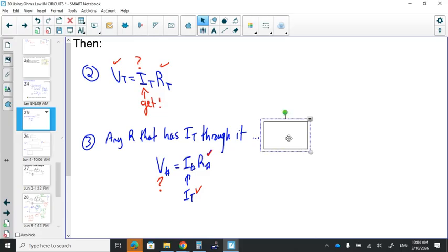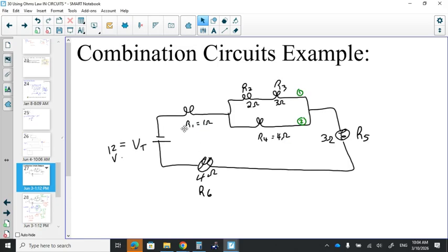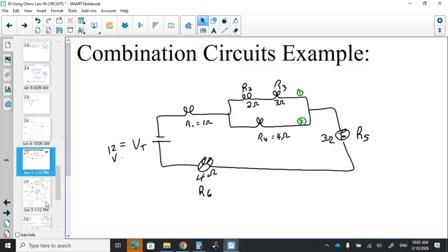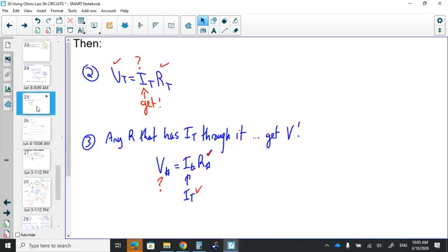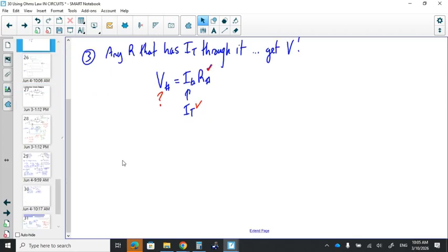So, for example, in this circuit, the weird one here, once you have how much current is flowing, well, then you can find out how much voltage dropped here. And you can find how much voltage dropped there. And you can find how much voltage dropped there. And then the remainder of the voltage is going to be dropped across this one for sure, and across those as a group for sure, right? So just putting it all together, it becomes not as bad as you might think.